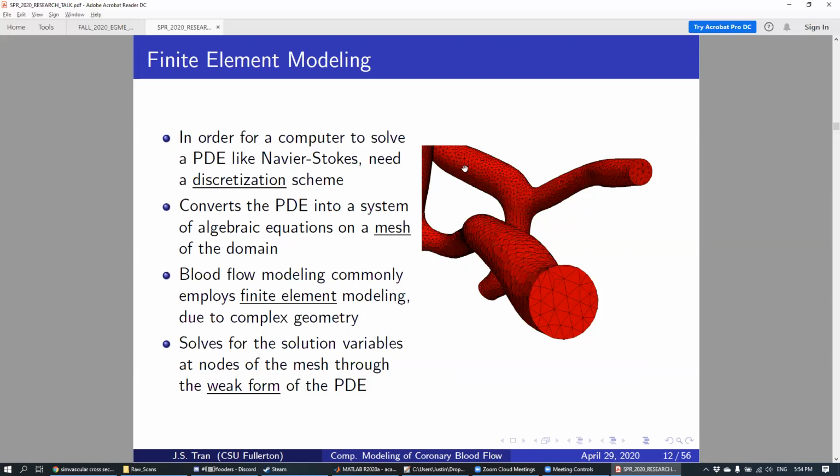And so if you're kind of familiar with the world of CFD, there's actually a lot of different methods out there for solving the Navier-Stokes. And so what's actually more common outside of this particular field is to use a method known as the finite volume method. And so the finite volume method is a method that's really nice for fluids, because it's a method that's conserving. And so that means that conservation of mass is kind of automatically preserved, or satisfied.